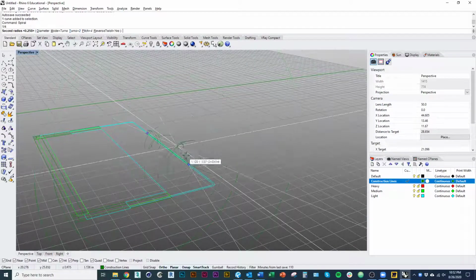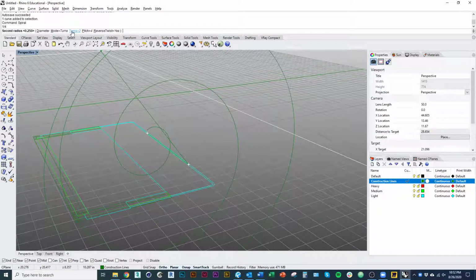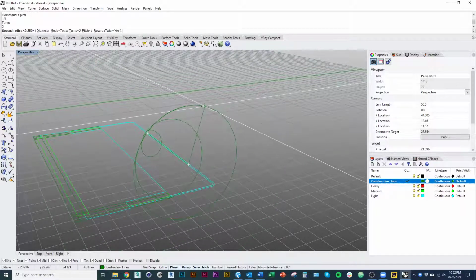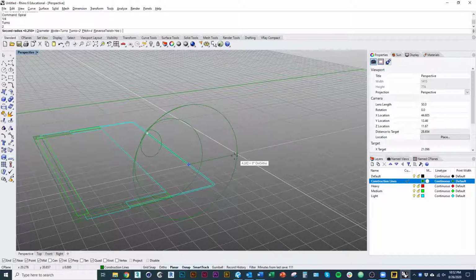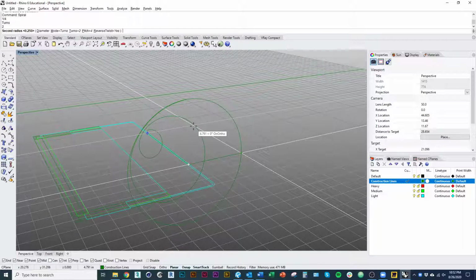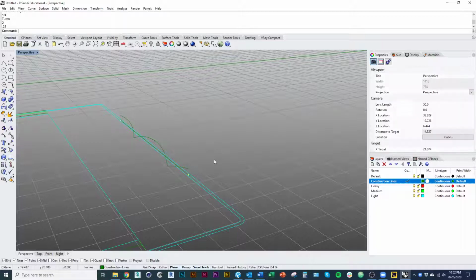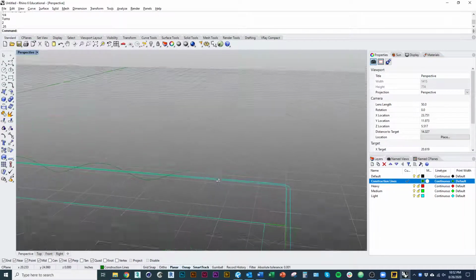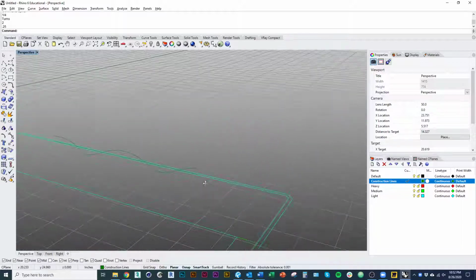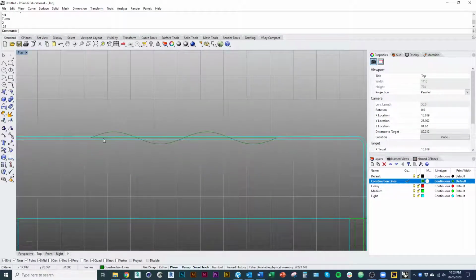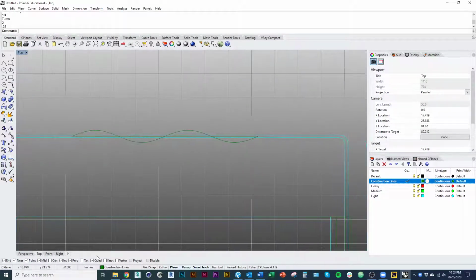Oh, by the way, like I said, it's 720 degrees. So this option here where it says turns, you'll want to enter 2 there. And that'll be 2 full turns or 720. And again, we're going to type in a dimension, 5, and it should automatically, because we've already set the turns, know where it'll end. And so now you can see we have a 3-dimensional spiral wrapping around that central line. And if we go back to our top view, it looks pretty much like we would need it to look, right?